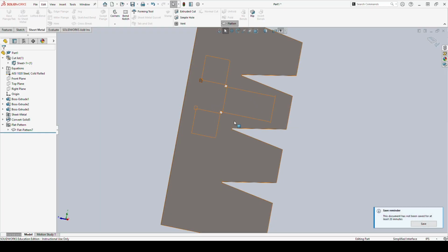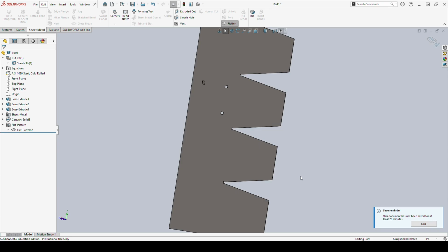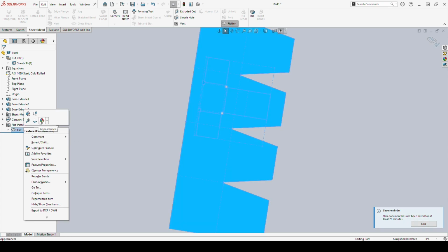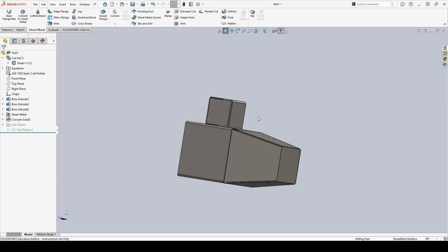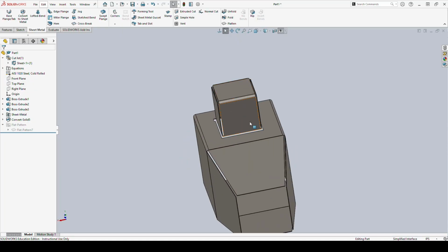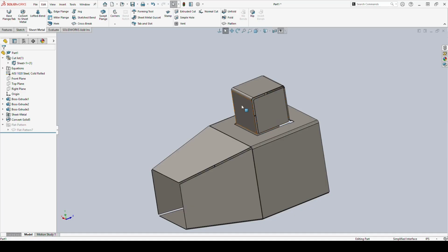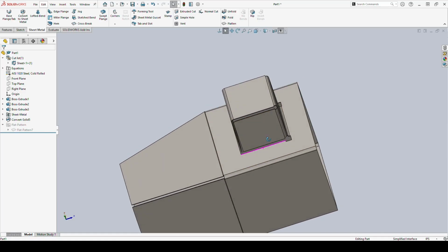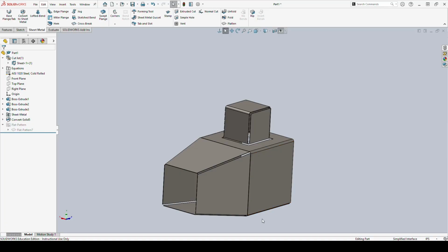That is probably the most common mistake that we're going to see. Things like this where it's just this little notch here that looks perfectly reasonable. It's just not something that can actually be made in real life. And SolidWorks, well, SolidWorks isn't always real life. We got lots of opportunities to add different things, different assemblies that you'd actually have to have 3 elbows if you actually wanted to tighten down and fasten.